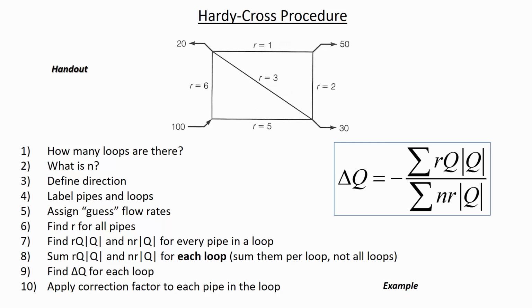Whatever flow rate we determine for these two pipes has to add up and equal 100. And so we could just say split it 50-50, or we could try and make our solution converge a little faster, and say 60 through this pipe and 40 through the other, under the rationale that the pipe that has less resistance is going to experience more flow.